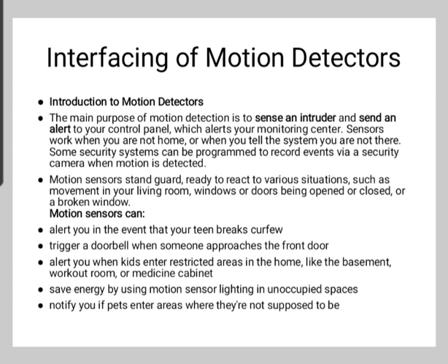Then the next, microwave. These detect motion through the principle of Doppler radar, and are similar to a radar speed gun. A continuous wave of microwave radiation is emitted, and a phase shift in the reflected microwave due to the motion of an object towards or away from the receiver results in a heterodyne signal at low audio frequency.